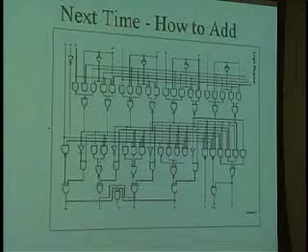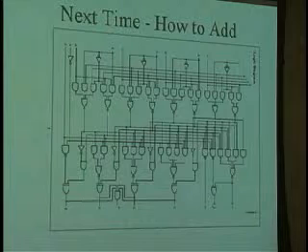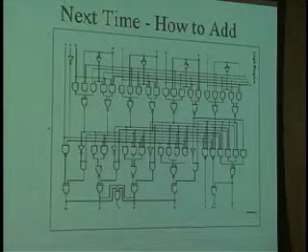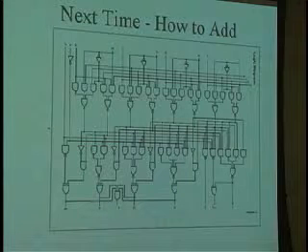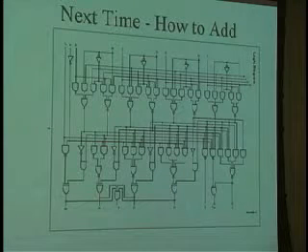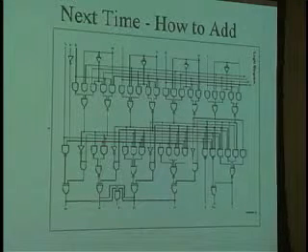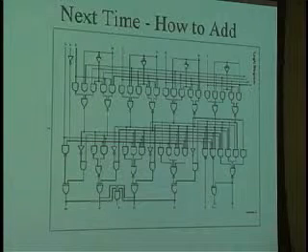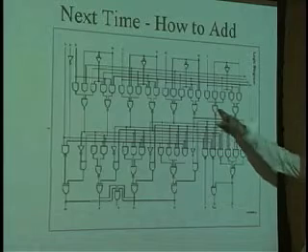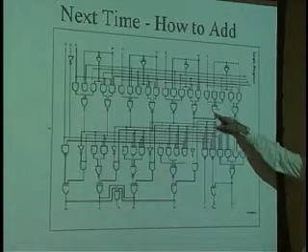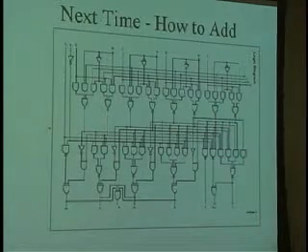The other thing we're going to do the next time is we're going to talk about a circuit that looks like this. And again, you open the hood of a car and you look at this and you say, oh my God, right? It turns out that this is a 4-bit ALU, okay? And these things over here are AND gates that do AND. These here are NOR gates, which do OR and then take the inverse of the output.